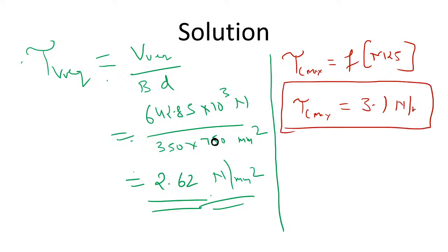So it means the developed value of shear stress is less than the maximum permissible value of shear stress with reinforcement. So I can say it is safe, means your section does not need revision. Okay. So guys, it's an important question for understanding the concept of torsion. So let's proceed further. We have completed our step number 1, calculation of equivalent shear and the check.